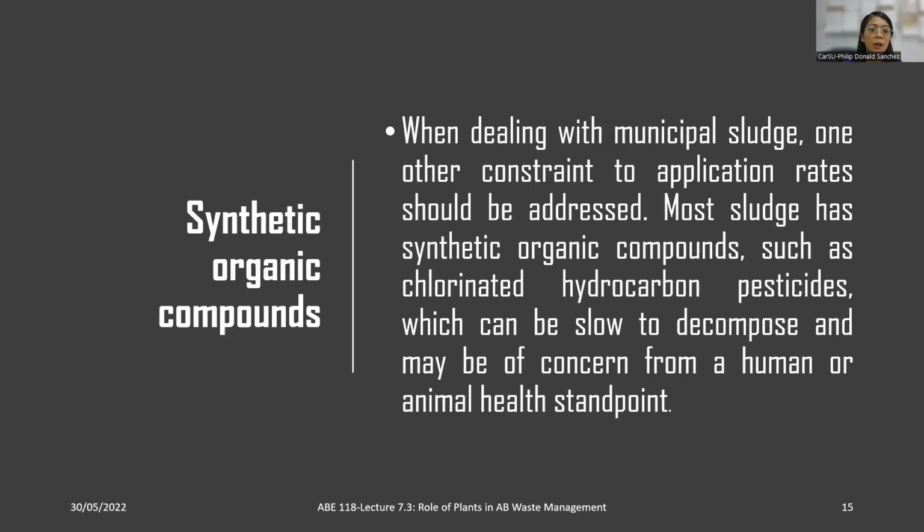So, synthetic organic compounds. When dealing with municipal sludge, one other constraint to application rate should be addressed. Most sludge has synthetic organic compounds such as chlorinated hydrocarbon pesticides, which can be slow to decompose and may be of concern from a human or animal health standpoint.